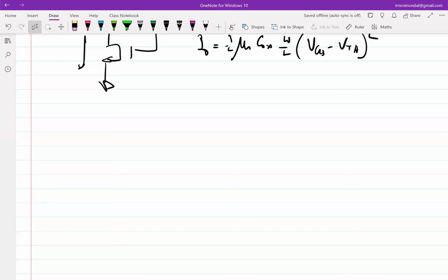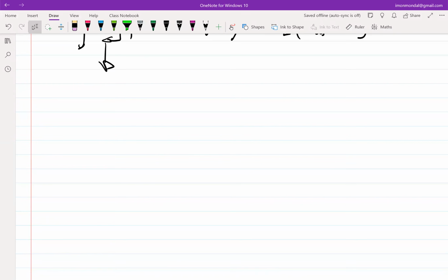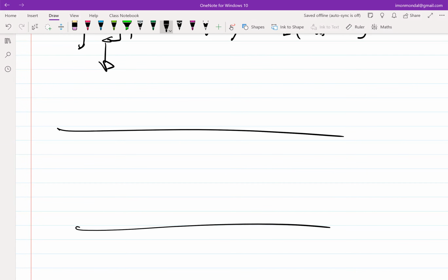But that's not actually the case, because the wafer in which you are building your transistor has a single P body. So all the NMOS transistors sit in a single common well. You cannot say that one NMOS transistor has a different body voltage than the second NMOS transistor. So essentially your NMOS transistors will all sit here.